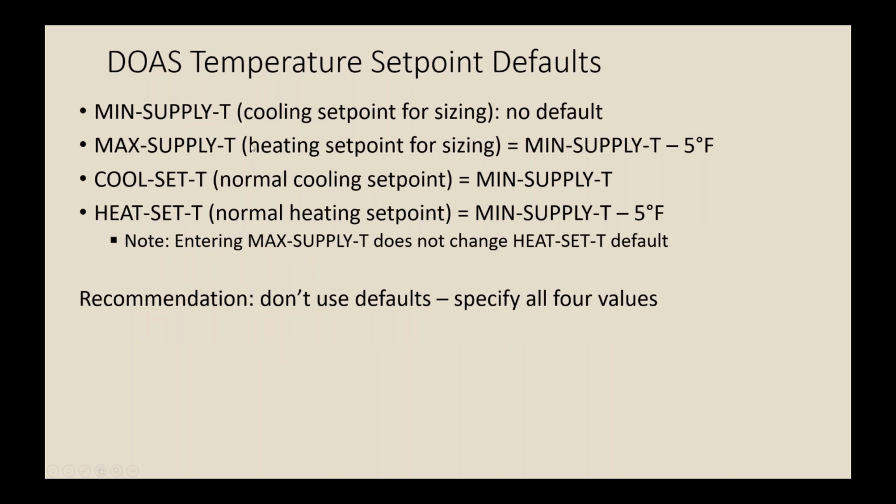This is a little discussion of temperature set points for the DOAS system and the defaults that are set automatically in the program. I found this to be a little confusing when I started working with it. Basically, there is no default for the min supply T, so you're required to set something for that as long as there's heating or cooling delivered by the system.